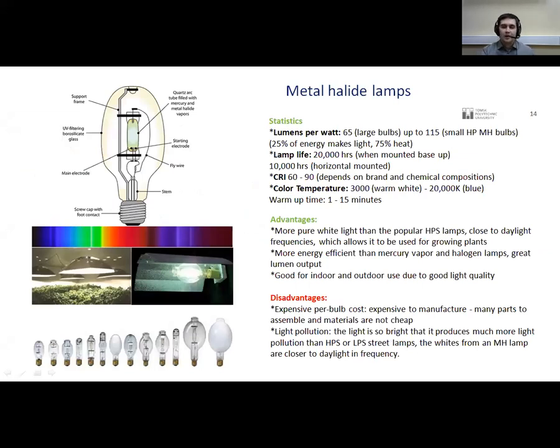especially in horticulture. The metal halide lamp is a modified version of the high pressure mercury vapor discharge lamp. Inclusion of metal halides along with the mercury vapor and inert gas permits optimization of the spectral quality of the emitted radiation. Metals such as sodium, scandium, indium, thallium, and dysprosium are used in this type of lamp due to their characteristic emission spectra in the visible range.